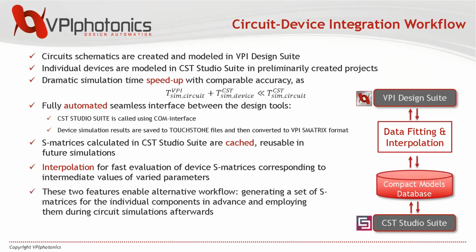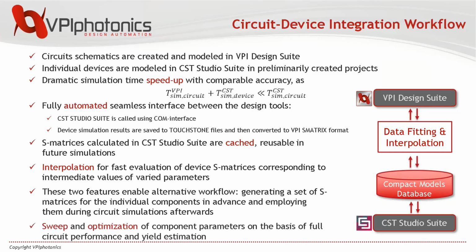And this means another approach is also feasible. So you can generate a database first with CST Studio Suite and then reuse it in simulations. And together with small simulation times, interpolation and caching features permit to perform optimization and tolerance analysis, which usually involve hundreds and thousands of simulation runs. So fast simulation really matters.